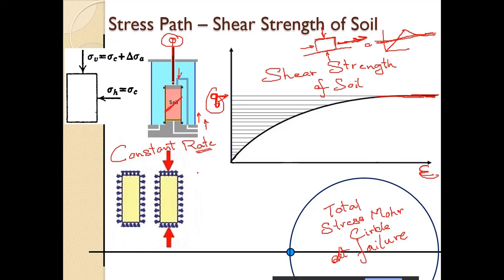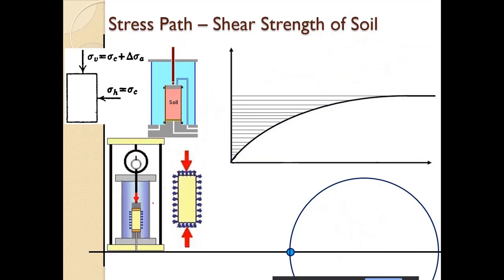As we have discussed, we are actually measuring the reaction from the soil. The soil has already failed, it is constantly shearing, and it cannot give any more load. It cannot compress the proving ring any further. Therefore, whatever load the proving ring is giving right now at this point is sufficient to keep the sample shearing at the rate it is going up.